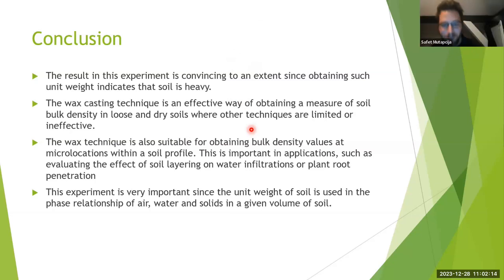Yes. Usually when you're expecting compaction of the soil for the foundations, you're going to do a Proctor test. That's one test specified to define what's called the optimal water content for the compaction, because soil is going to compact differently based on the water content ratio.